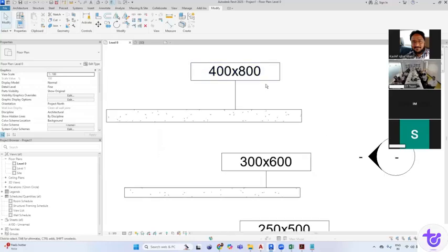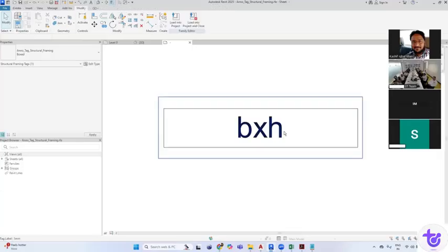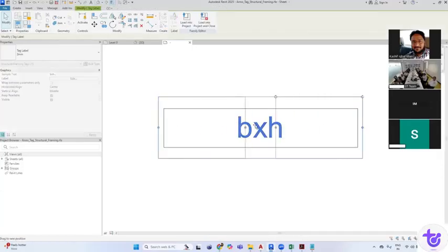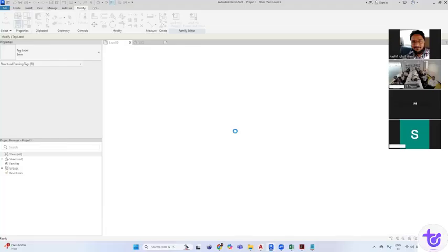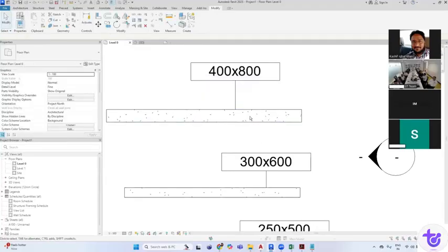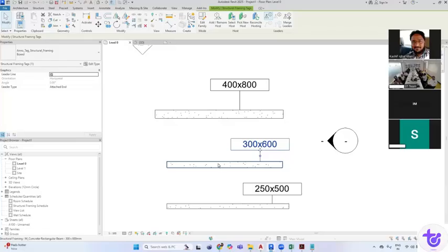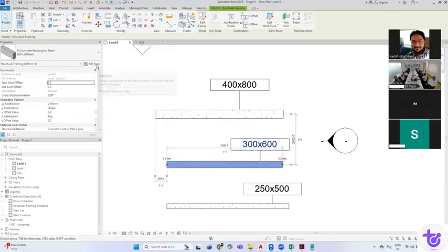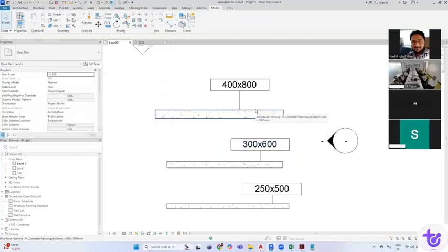We can increase the gap, we can decrease the gap, or also we can stretch this window or compress this window. This is up to us because this is not the subject, so I was not putting more light onto it. Anyways, if anybody has any question about the importance of having a shared parameter instead of this family parameter, it was not at all useful, which was previously set by default. It was not useful when you were not able to put the value in the schedule. You were not able to tag them properly. It was only dependent on the type name of the beam.